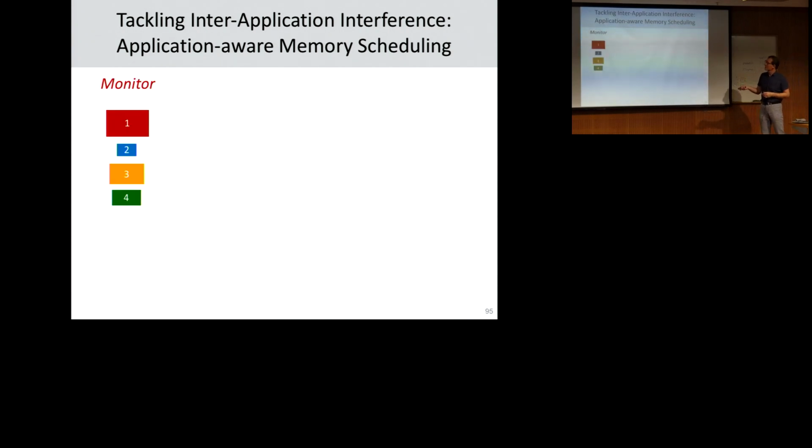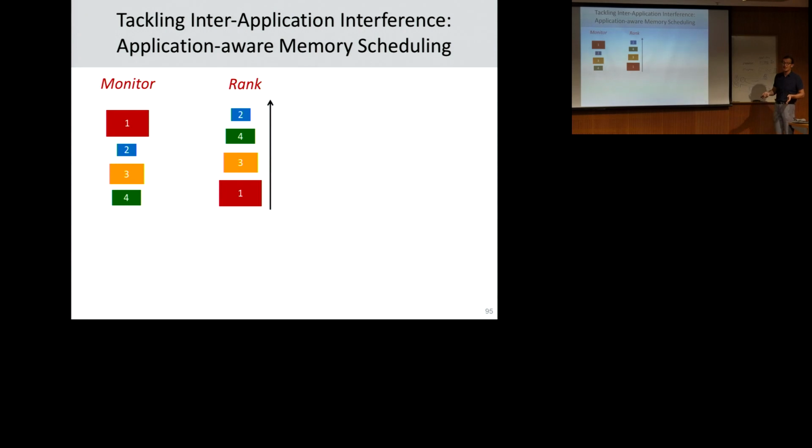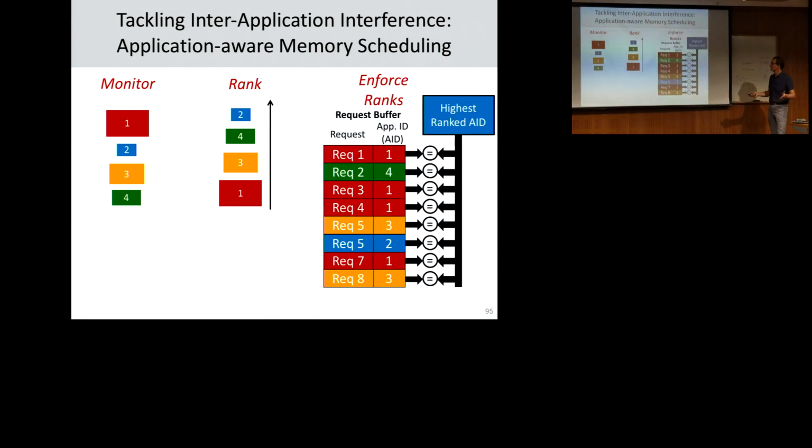So basically, let's take a look at what we've done so far. Basically, we've developed a lot of application-aware memory scheduling mechanisms, or you can call it thread-aware memory scheduling mechanisms. And memory scheduling has become thread-aware. It's aware of the threads. It monitors the behavior of the threads. It forms a ranking of the threads. And I motivated the principle of ranking, which is a good principle.